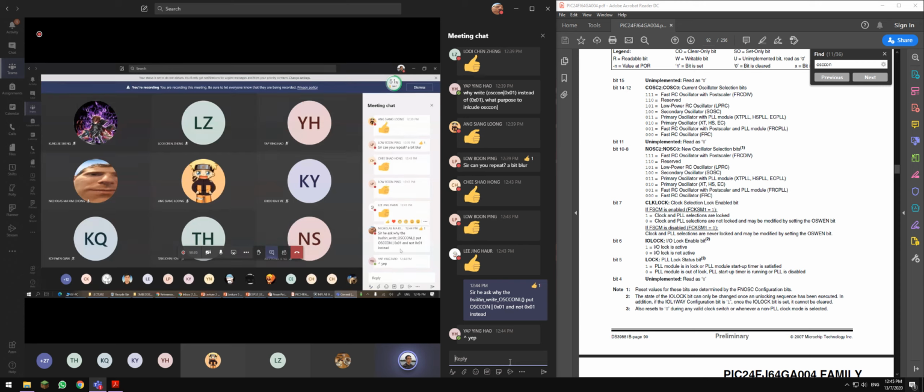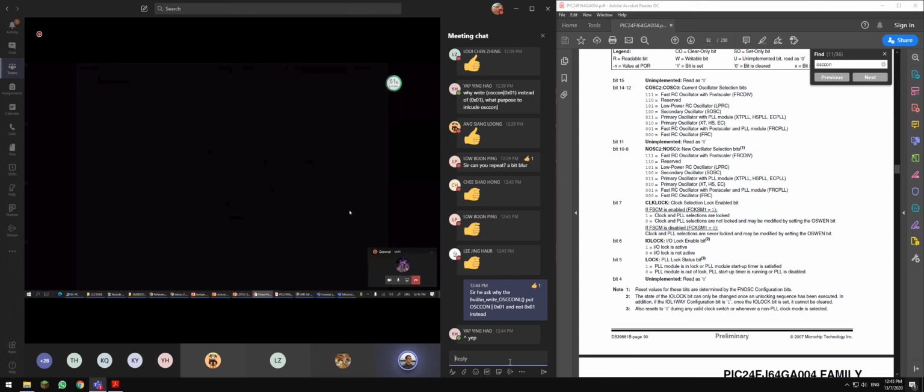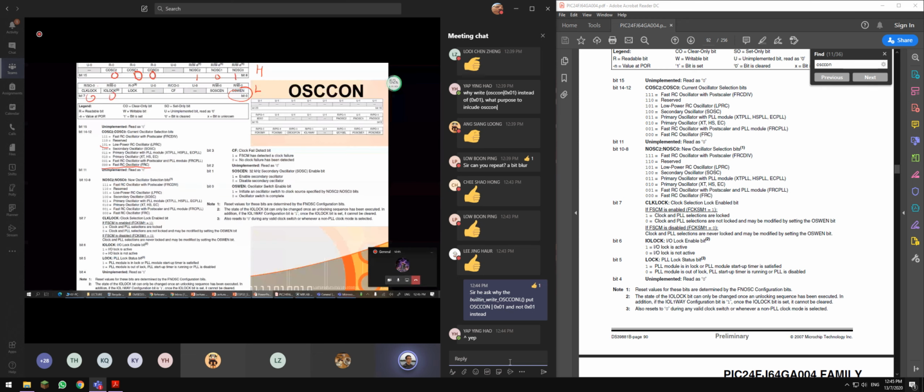why the built-in function uses OR and not AND? If I put 0x01, my dear, if you don't put this, you put 0x01, means what? Means this. Indirectly, you are changing all this. Are you going to change this? You want to put this all 00001? No. You want to OR it.